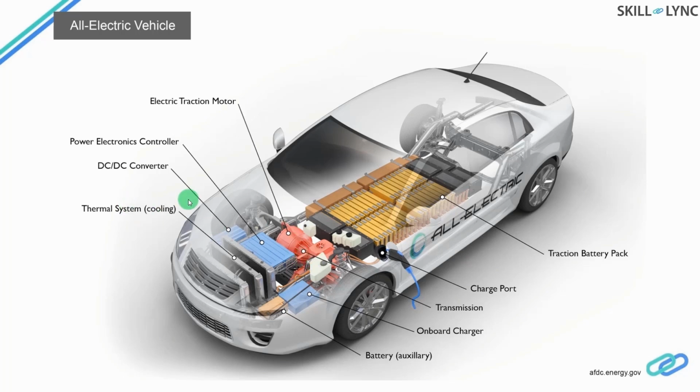Now, in the case of a gasoline vehicle, the thermal system, the cooling system, is primarily used to cool the IC engine. But here, there are so many things that you need to take care of. You need to make sure that all the power electronic components and batteries are maintained at reasonable temperatures, because all these components are sensitive to temperature and their efficiency drops pretty badly if their temperature exceeds their normal range of operation.